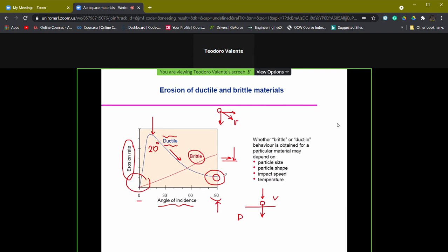That depends on the application we have in mind, because in the case we use this effect positively at 90 degrees, the particles are embedded on the surface inside the material. So we are changing the surface material composition, and we are changing, generally speaking, the surface material's chemical and physical properties. And so we must ask ourselves if these changes can be accepted for the special function to which our component has been designed.